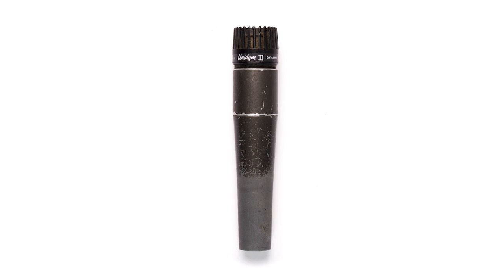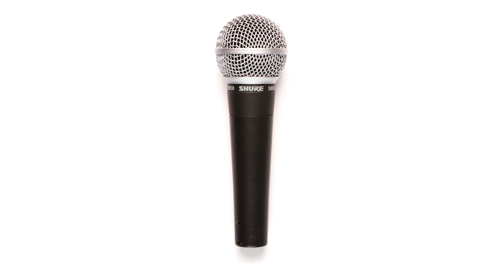Microphones convert acoustic energy, sound, into an electrical signal. The topic of microphones is complex, and for this course, we are going to focus on a few basic types of microphones. Microphones are often referred to by how they work, dynamic, condenser, or piezo, and by their directional characteristics, cardioid, omni, shotgun. Two of the most common types of microphones are dynamic and condenser. Dynamic mics are highly dependable, rugged, and reliable. Dynamic mics function just like a speaker, only in reverse.